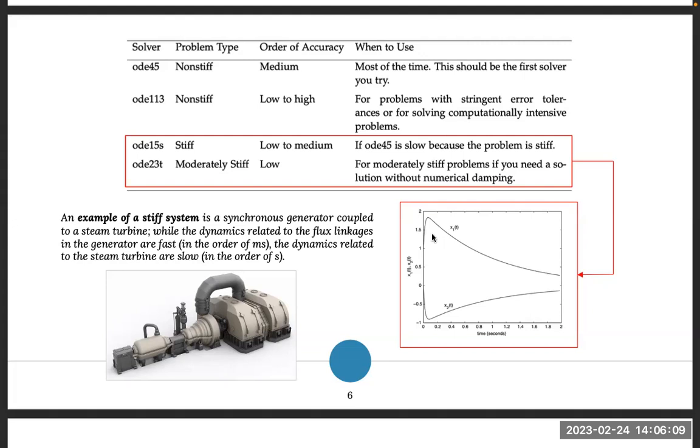However, when you want to analyze this, you can say, okay, the generator is too fast, infinitely fast. So I'm going to analyze what is going to happen in this scale together with the power system, but this thing is going to be ideal. It's going to move infinitely fast. So that's the subdivision that we have to make to use this ODE solver.